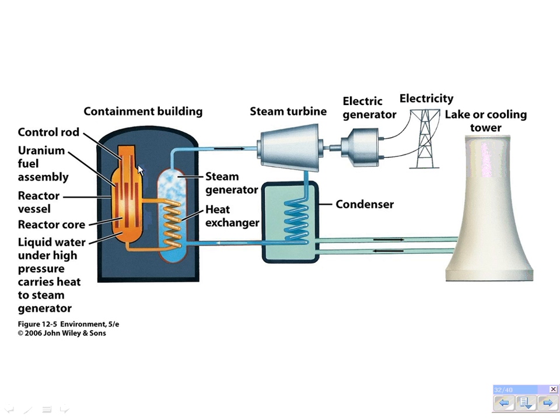Inside our reactor core, we have liquid water, which is under very high pressure. So that water is going to stay in a liquid state. It's not going to evaporate into steam. And you can see that it's going to move throughout the primary circuit. It's going to move in this direction over and over again. It's highly radioactive because it's coming into contact with the reaction itself.